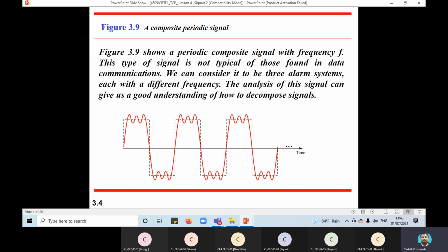So if we can think about trimming all these high frequency components, or just making it equalized to an average flat value, if we can flatten this edge, that will be suitable for data communication, because we have a flat edge and a negative flat edge. So we have basically two levels that we can interpret as ones and zero logics for it. So you have a dotted line representation here.